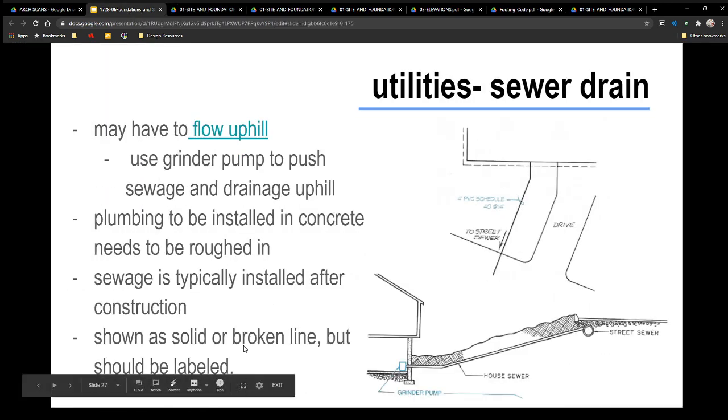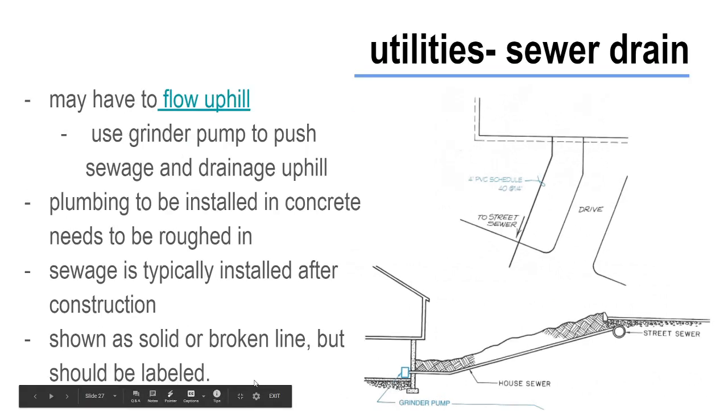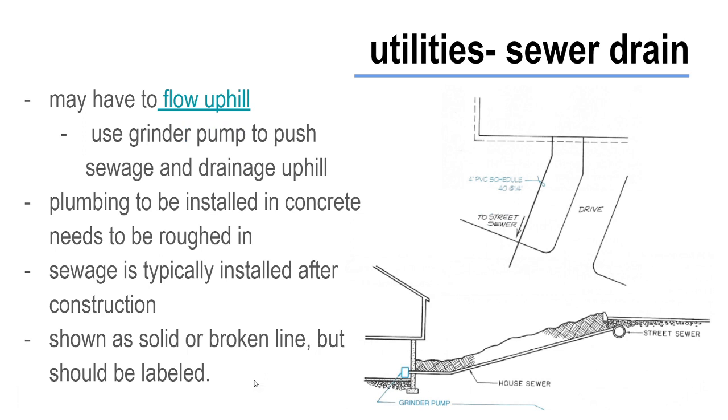And that's when you would use a grinder pump to help push the sewage or drainage uphill. The grinder pump grinds solids into small enough particles to be pumped as sewage with fairly low pressure.